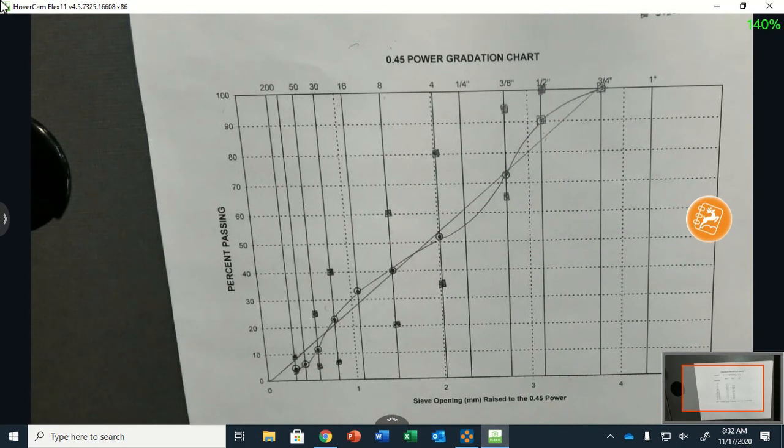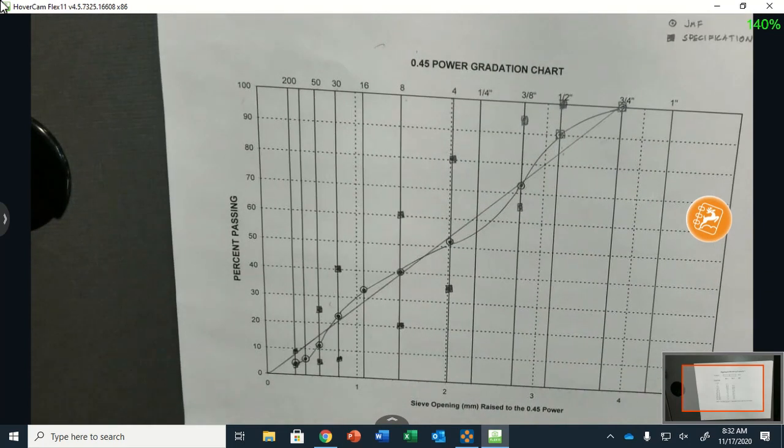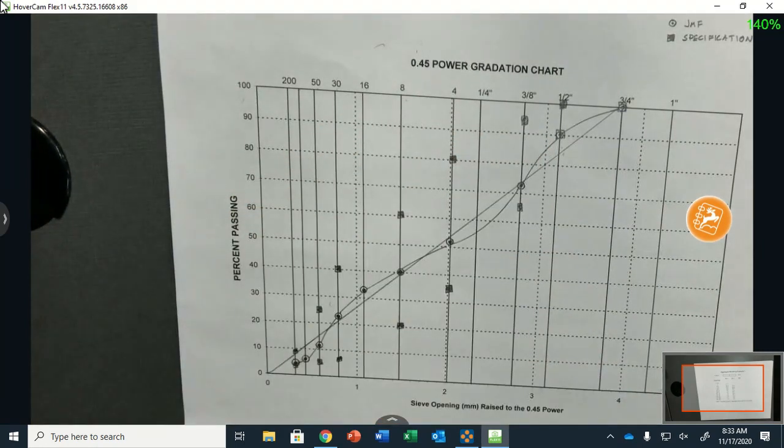I mean, like, okay, Northeast Asphalt calls McKeefrey, hey, my number 8 sieve is off. Okay, I'll change that, right? And the next load is fixed. No. So they have time, for the next couple of sample intervals, however many tons that is, they should see a correction. If they don't correct it, then based on the percentage within limits, the percentage of that control point, they'll get a deduction in pay. Okay, they'll get warnings basically.